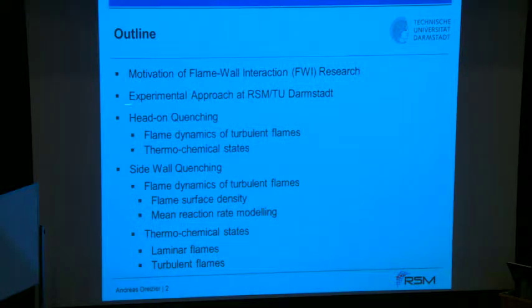And you will see that flame-wall interaction is divided into different classes that are called head-on quenching, where a flame is approaching, for example, like in IC engines, initially at least, a wall before it's quenched. So the propagation is against the wall, whereas in sidewall quenching, the idea is if you have a wall like that, the flame is creeping or moving along that surface. It's not always easy to distinguish these extreme and idealized cases.